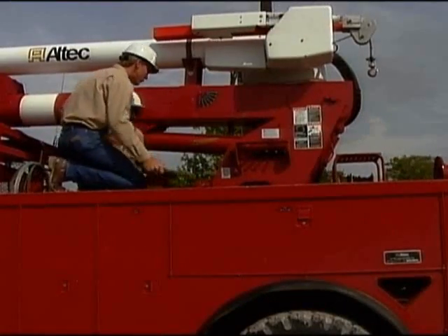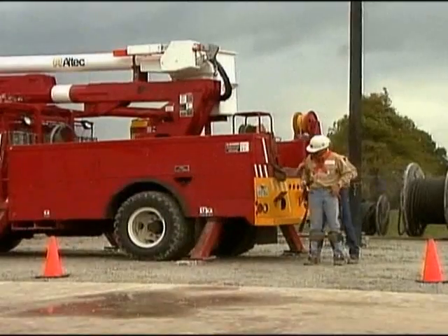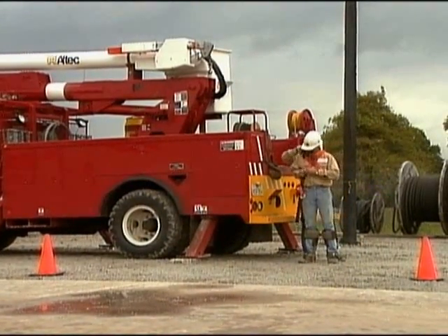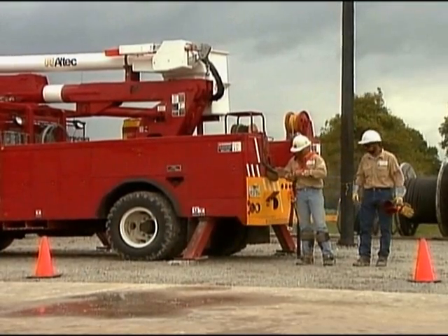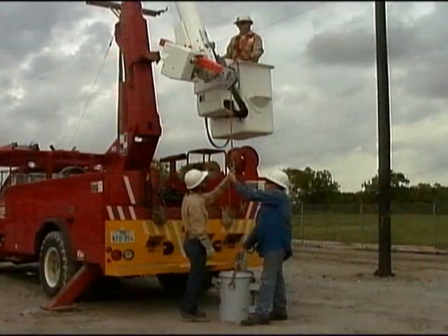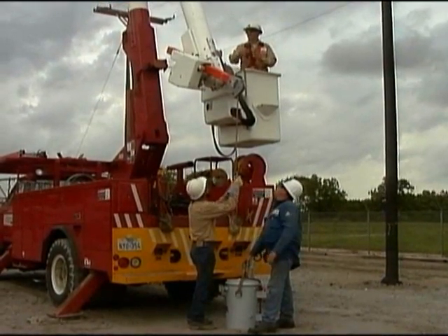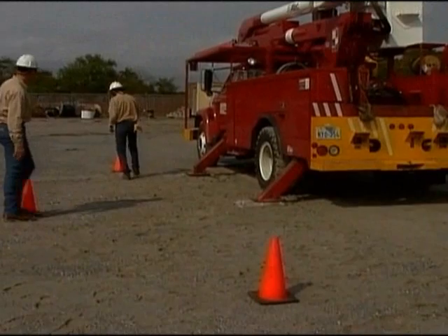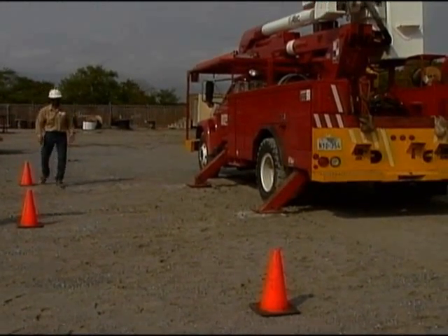Never work from a vehicle without knowing the limited approach boundary. Workers that are on the ground should never touch a vehicle or equipment unless they have the correct personal protective equipment. If the vehicle is intentionally grounded, personnel should not touch the grounded vehicle. Proper barricades should be used to prevent personnel from getting too close to the grounded vehicle.